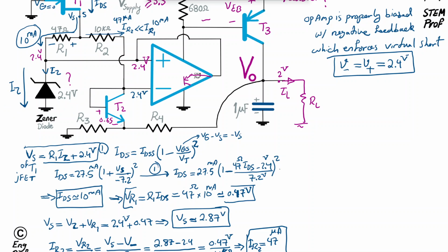So exactly what happens is the transistor T2, which is an NPN BJT transistor, is a low current one, because we just found that this is 47 microamp steady state going through this branch to get to the collector. Because it's a diode-formation connection, T2 effectively acts like a diode, so we just have the nominal VBE 0.65 volt at this current level appearing at the base emitter of T2, which means the voltage here, which I'll refer to as, let's say, Vx, I'm going to write it here.